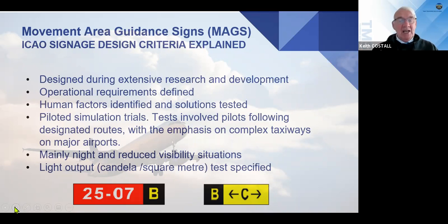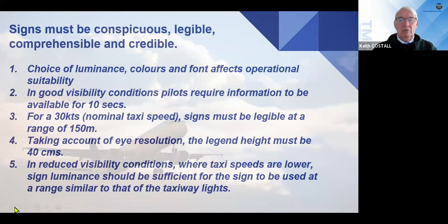That is where the size of the guidance signs themselves came into consideration, and the size of the letters and numbers on a guidance sign, etc. So all these were practical tests, the consideration and then the production, and then those practical tests with real aircraft and a real runway.